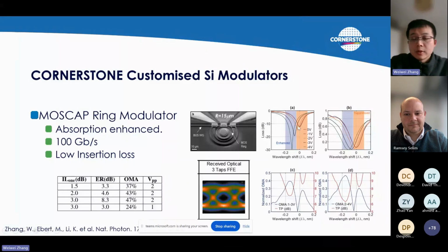So in this case, we will see a very large absorption in the modulation on the left side of the microring spectrum, and on the right side, because the spectrum is broadening when you apply an electric field, the right side will be more of a suppressed modulation region. So considering the nonlinear dynamics of the microring, the best option is always to set the laser wavelength on the left side of the microring, which will provide much more stable operation than the right side.